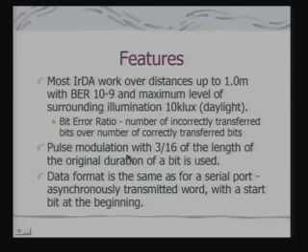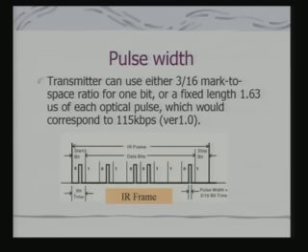Now pulse modulation with 3/16 of the length of the original duration of a bit is used. Data format is same as for a serial port when it is asynchronously transmitting a word with start bit at the beginning. So this is how the pulse width looks like.